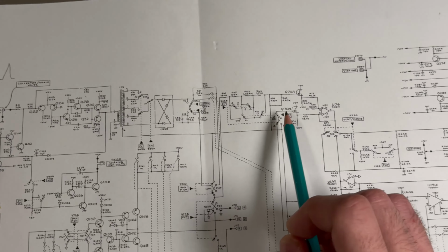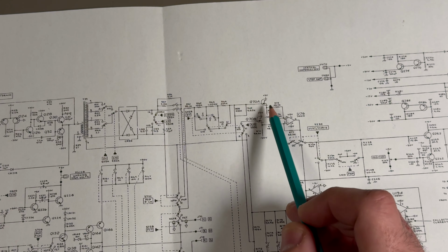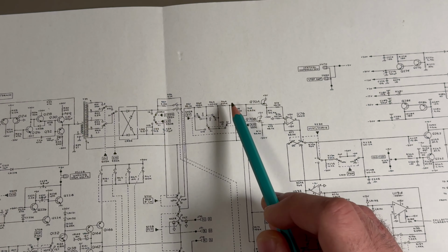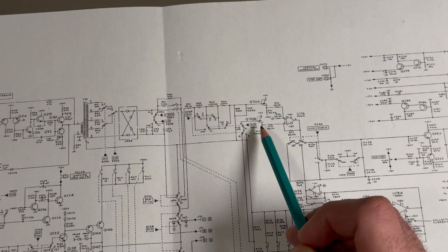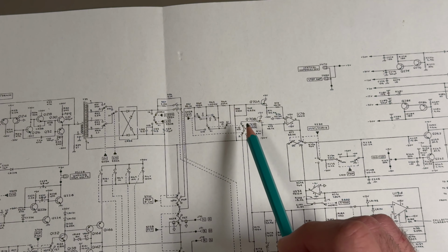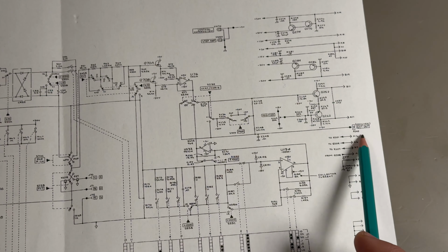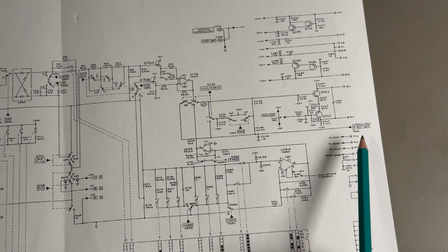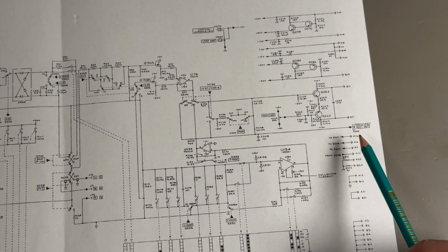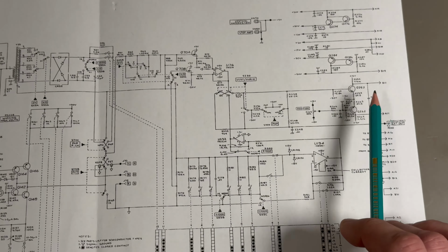Then you have a difference amplifier with a couple of source followers. These are high impedance devices. These are JFETs. And the difference amplifier basically measures the voltage across the collector emitter of the transistor. And this goes basically to the output. The output is actually a terminal, a BNC cable that you have to yank out of the instrument and plug it into a vertical amplifier in the Tektronix.